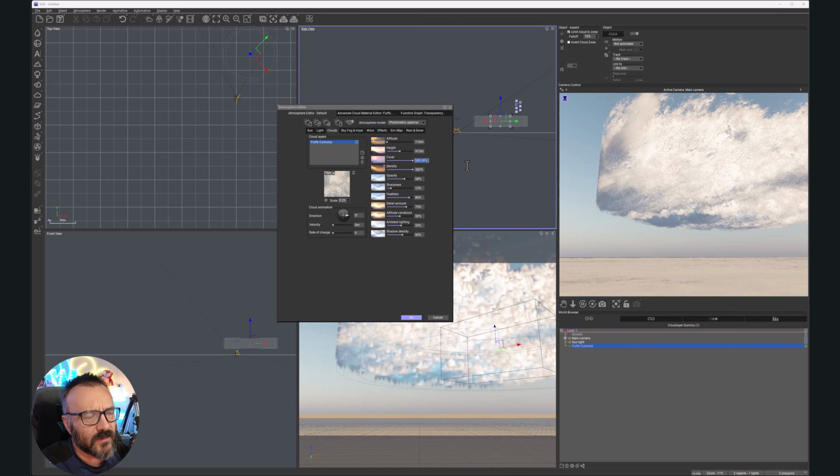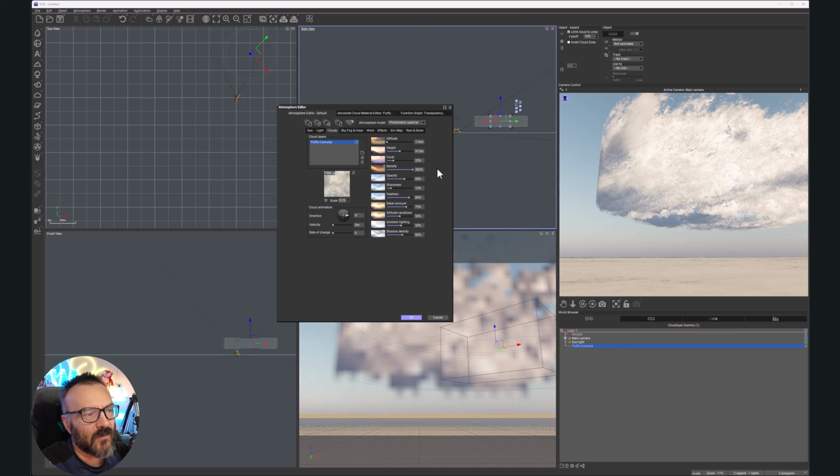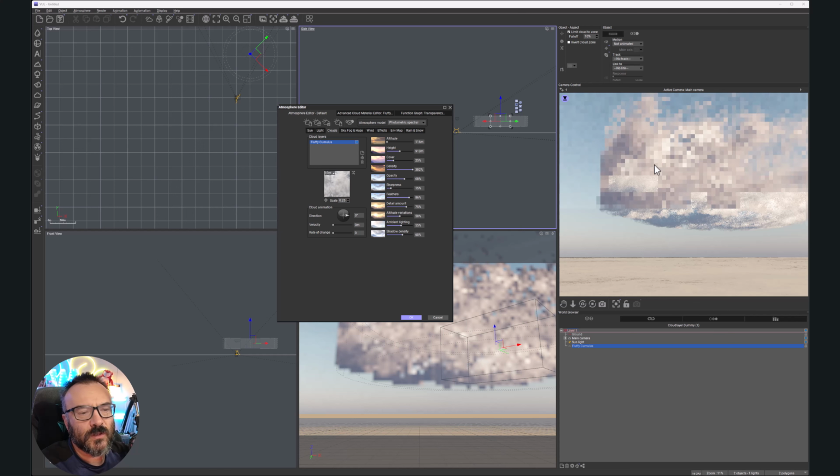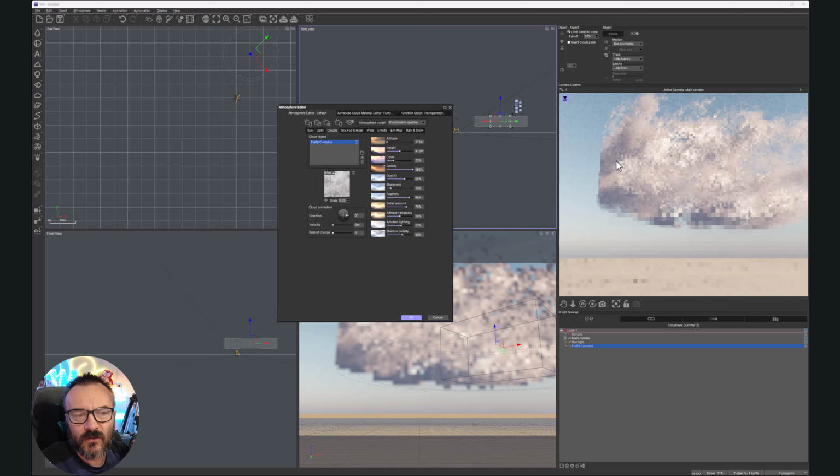Well, I don't want to have it this high, so I'm going to set cover to 25%. It will reduce some of this, and we can already see it looks nicer done this way. We have our density. Most of the time you'll notice in Vue they use density versus opacity because of how the rendering works.